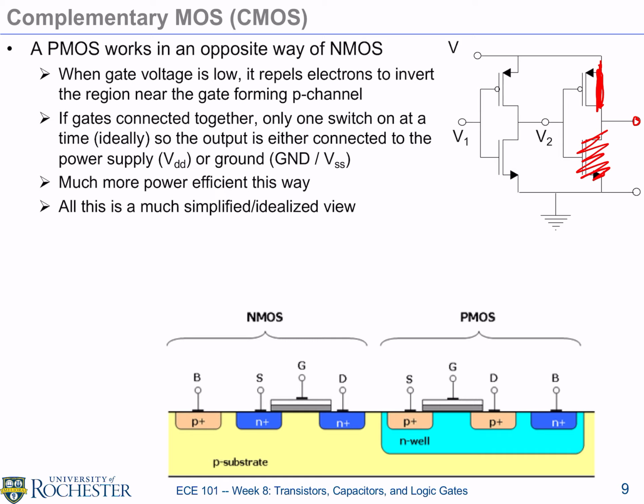In fact, for a split second, there is a transition, because the devices will all operate, right? Let's say V1 may be high. At some future point, the high may be transitioning to the low, and during that brief moment, one of the devices is trying to close, the other device is trying to turn on. You might have an overlap where both are somewhat on, and in fact there is a current in the analysis of the circuit that's called short circuit current.